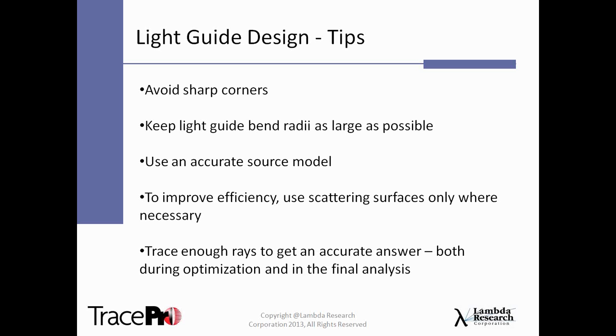Also, it's important, I believe, to use an accurate source model. The more accurate your source model, whether it's an LED or a fluorescent lamp or an arc lamp, the more accurate the results are going to be. This could be, say, using a ray file. You could download a ray file from an LED manufacturer. That can be used as part of the optimization process. Or a surface source property in TracePro with the angular and spectral distribution of the source.